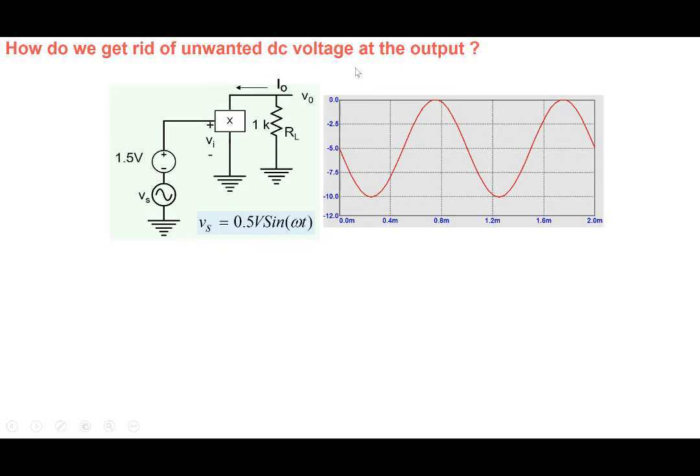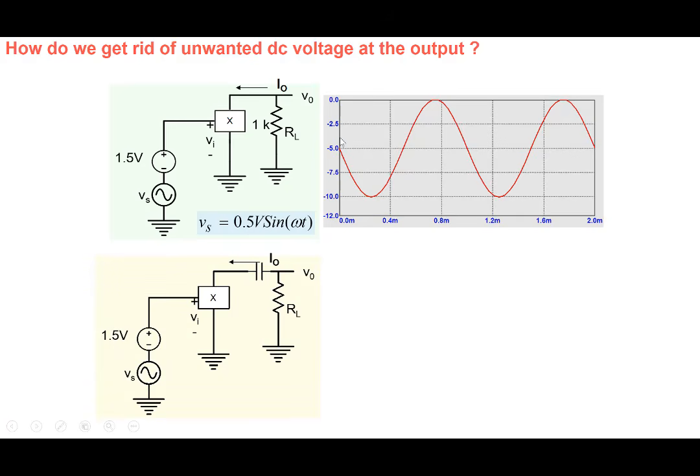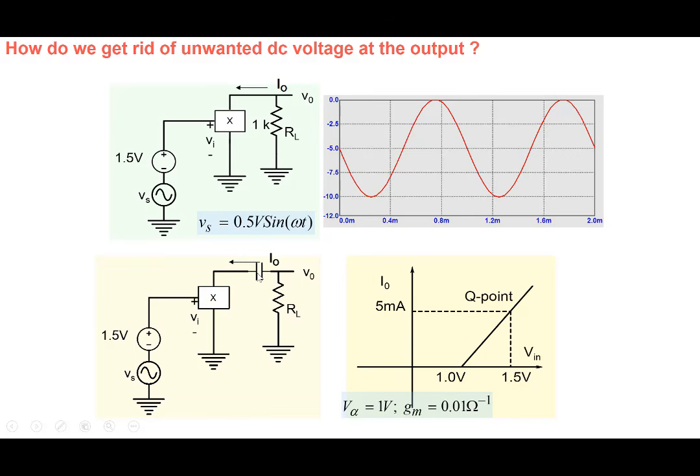So how do we get rid of the DC voltage here? Whenever you want to get rid of the DC voltage, we realize that a capacitor blocks any DC signal, right? So we could use a capacitor here. A simple thing, we may think, well, let's put a capacitor. We don't want DC current to flow through my load, and we want only the AC part here. So let's put a capacitor here. The capacitor is going to block the DC part here, but note that the moment I put a capacitor here...